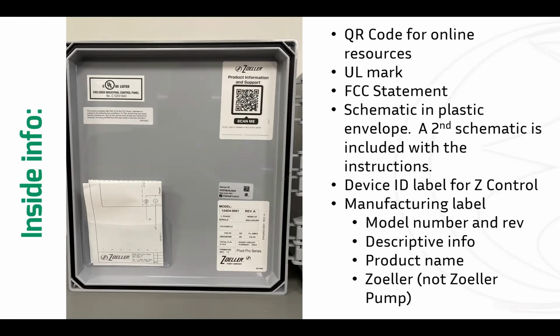It says, hey, write down the pump model number, write down the measured voltage, the measured load amps that the pump is pulling. So it's prompting them for information that maybe doesn't help them right that minute. It could if there's something wrong, but it certainly is going to help the next person that comes along to this panel and has to do service.